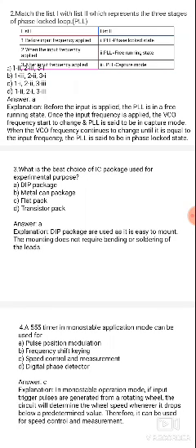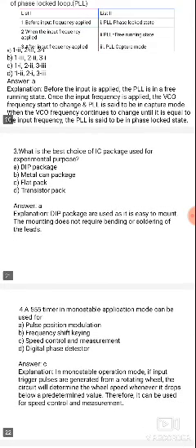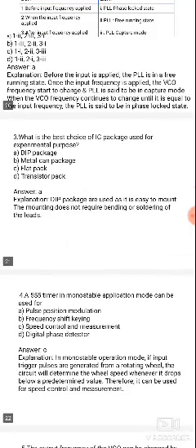The VCO continuously changes its output frequency until it equals the input frequency, and this is called phase lock. That's why the answer is: no input is free running, some input is capture range, and after input is locked range.